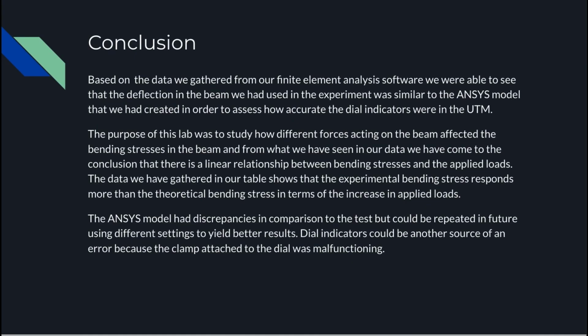Based on the data we gathered from our finite element analysis, we were able to see that the deflection in the beam we had used in the experiment was similar to the ANSYS model that we had created in order to assess how accurate the dial indicators were in the UTM.